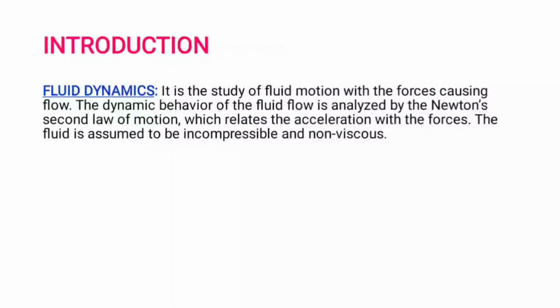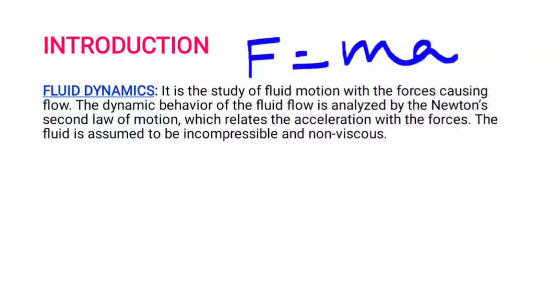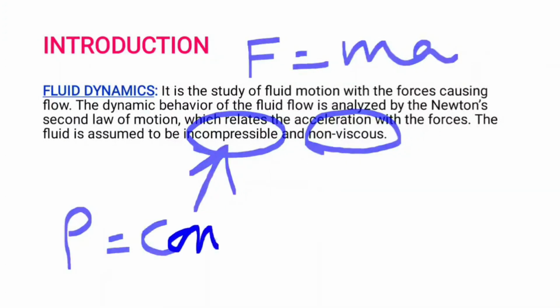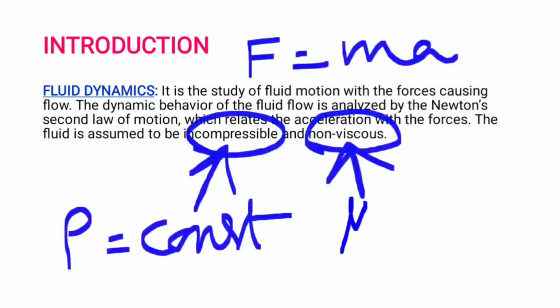The dynamic behavior of a fluid flow is analyzed by Newton's second law of motion, that is F equals ma, which relates the acceleration with the forces. The fluid is assumed to be incompressible and inviscid. Incompressible means the density is constant. And non-viscous means the viscosity is zero, that means frictionless.